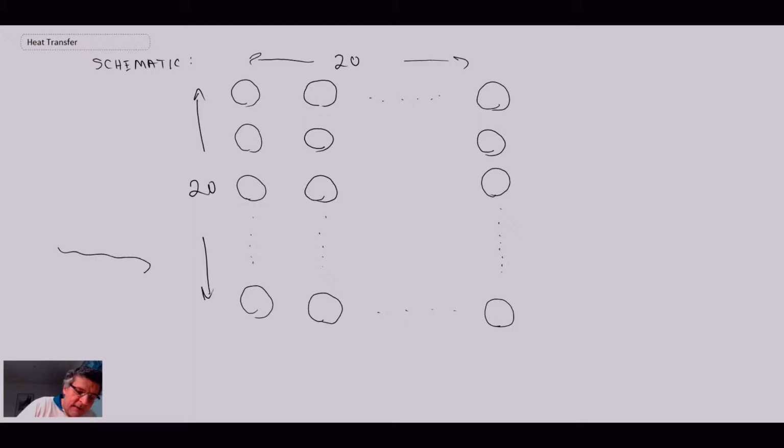Outside of the tube bundle, we have steam at atmospheric pressure and saturation temperature 100 degrees Celsius. Just like we talked about for tube bundles, we'll get a film forming that's going to drip down, and the film is going to get thicker and thicker. Eventually we have a very large film coming out of the bottom.